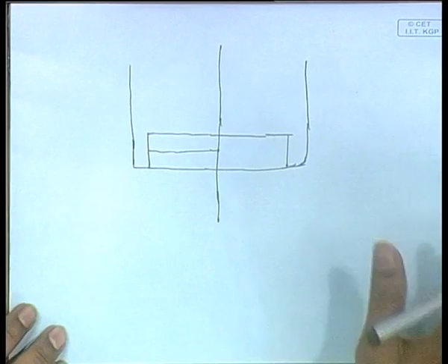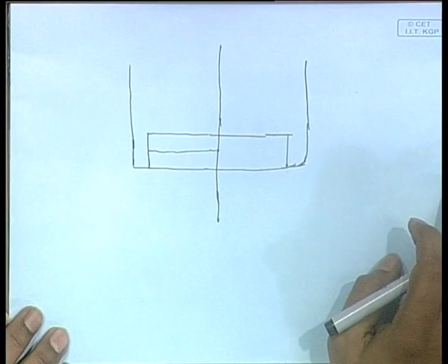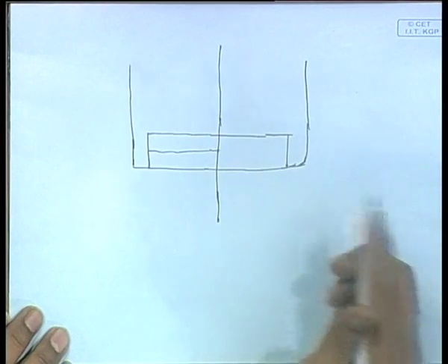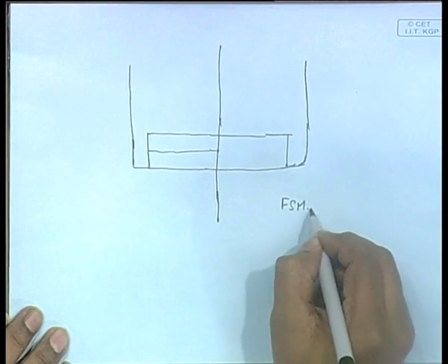If it is full of fresh water, there is no free surface effect. But let's assume something: it means it's not full, the tank is slightly bigger. So there is a free surface effect. So that is the problem, it is a free surface effect problem, and we have to consider that. So first of all, you have to find the free surface effect or free surface moment.